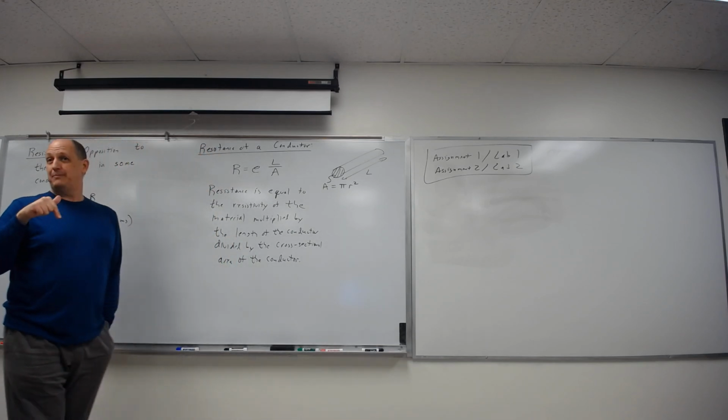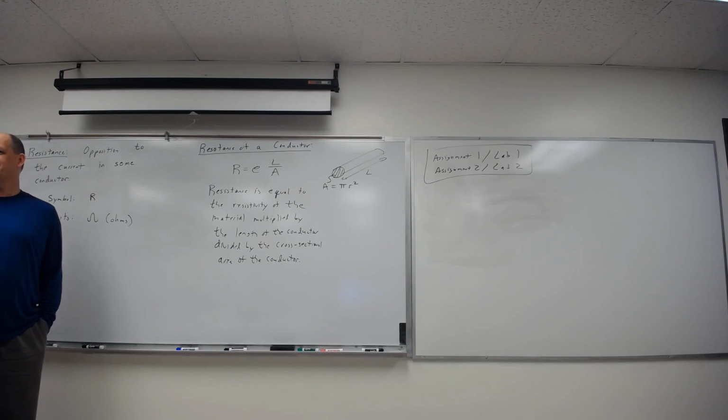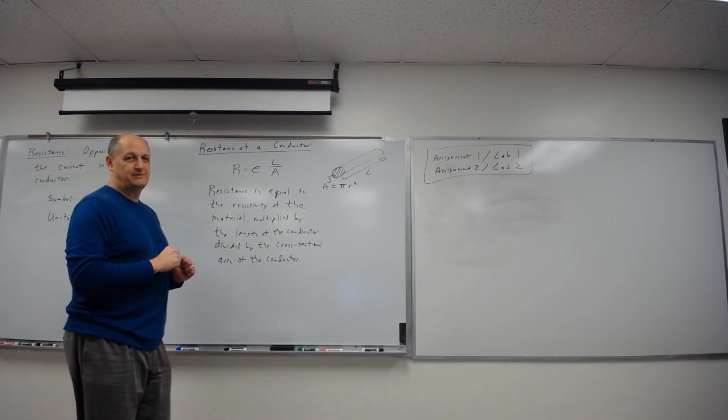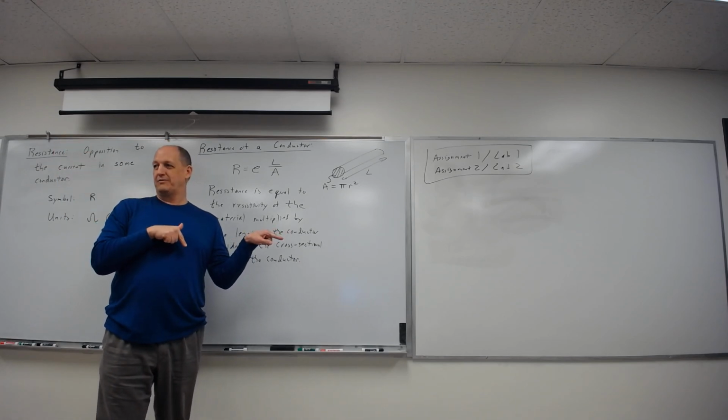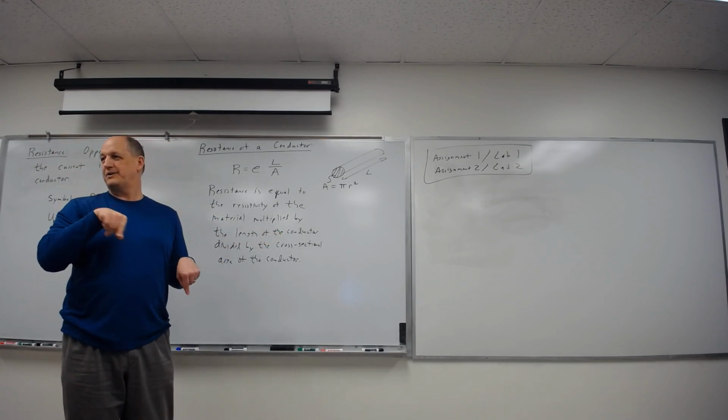Okay, this week in lab, measuring current. Last week was measuring voltage. This week's measuring current. So remember, break the circuit, measure right at the spot where you broke. Do not do anything where you try to connect my battery from positive directly to negative through my ammeter. If you burn my fuses up, I have the right to grouse at you about it.